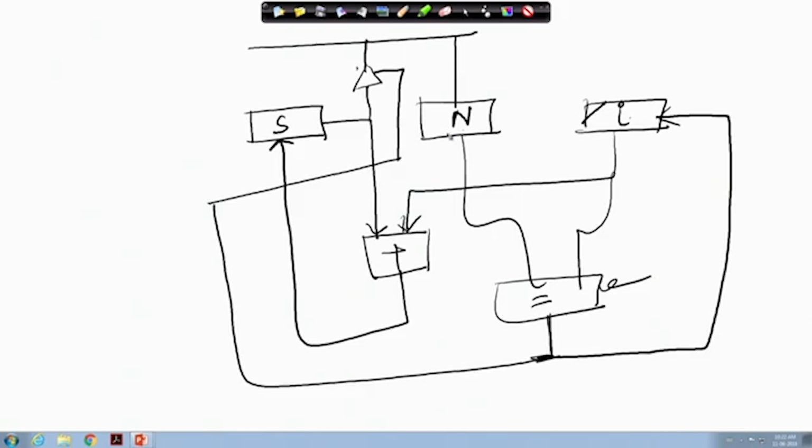The loop has done its job. So, now you just produce the result at the output bus. So, how can I do that? This is the terminating condition, that means whenever the n and I values are both the same, at that time it will come. This is just a single bit, as this is a comparator. So, this will produce a single bit output. That single bit output will come here and it will activate this buffer, so at that time this S will go to the external bus. So, this is the external bus.